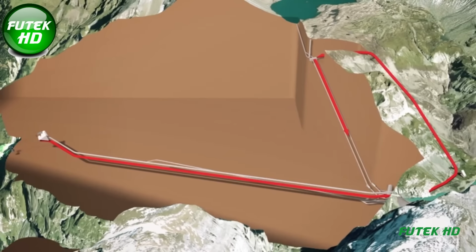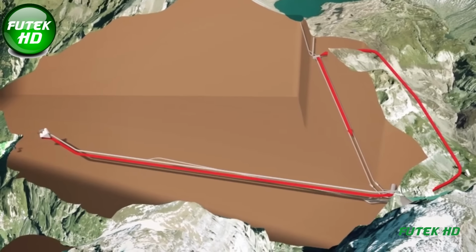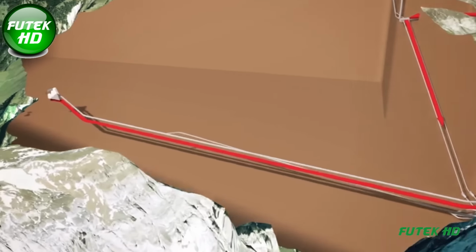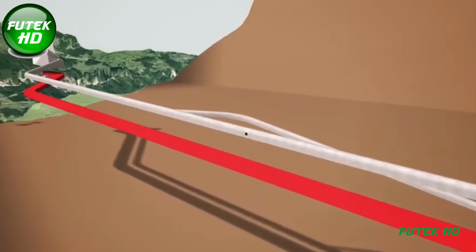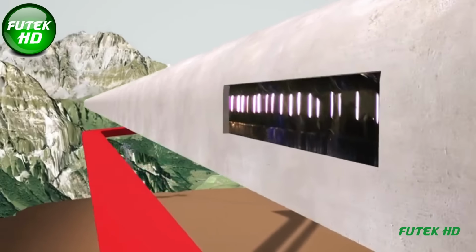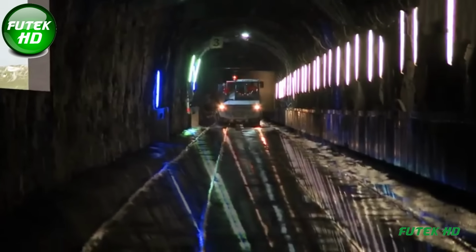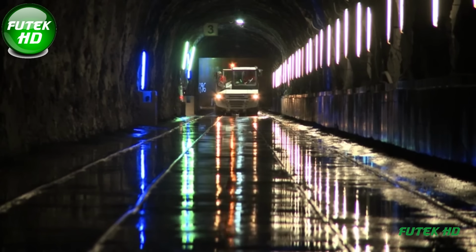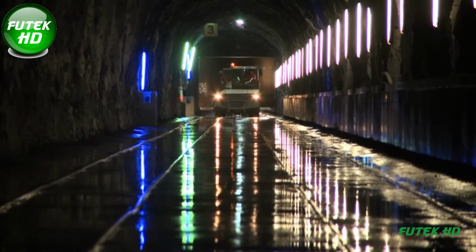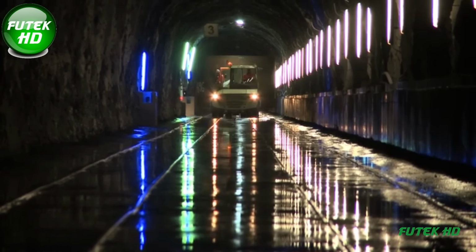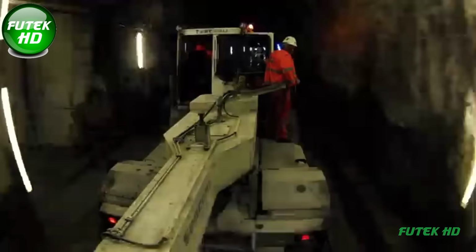This pre-assembly reduces the number of welds needed during the final installation in the pressure shafts, which are inclined at a 40-degree angle. Working in these steep shafts is physically demanding and requires skilled labor. Each weld in the shaft is carried out manually by expert welders, known for their precision and craftsmanship.